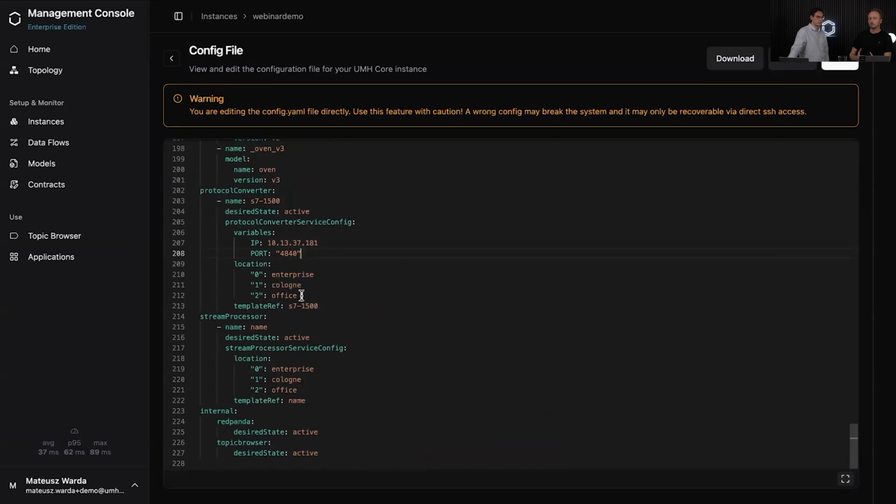So if you work with this config file, you would only create like 1 to 2, for example, especially like Modbus templates. Yeah, typically you always have the same 5 to 10 data points you want to read out. You have a lot of times the same Modbus devices, you would have it once in the code, and then always reference it to a new protocol converter, and then just fill in these dynamic variables here, which is going to make it also leaner code-wise and easier to manage.